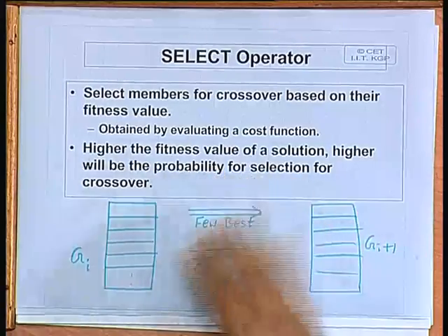Okay, fine. So, this is the essential idea behind the genetic algorithm, and some people have also tried to apply this. Is this used widely? This is not used in commercial tools, but there have been a number of works reported where placement was solved using genetic algorithm. The results obtained were good, but the time taken to arrive at the solutions was much higher as compared to simulated annealing. So, in practice people do not use genetic algorithm for placement.